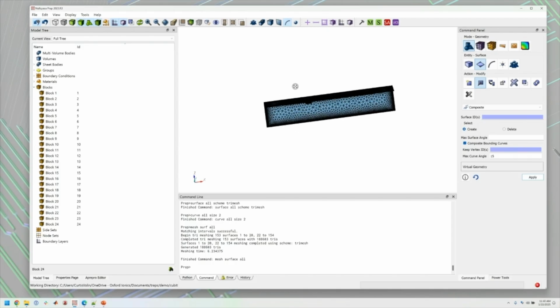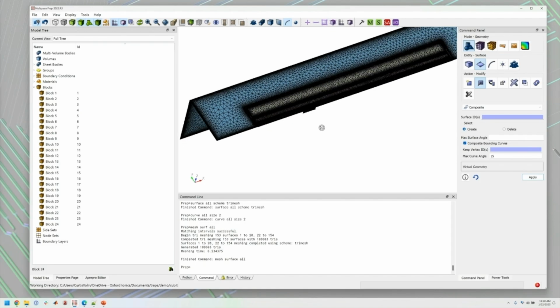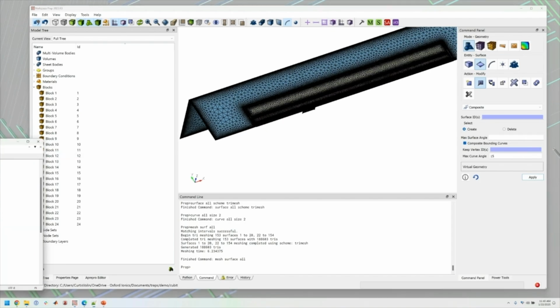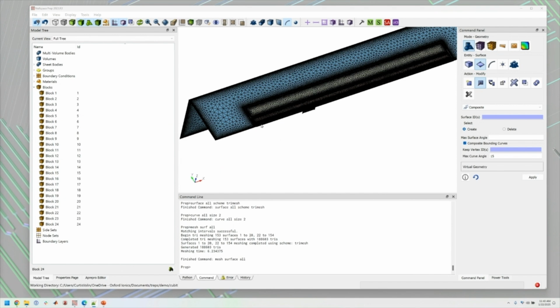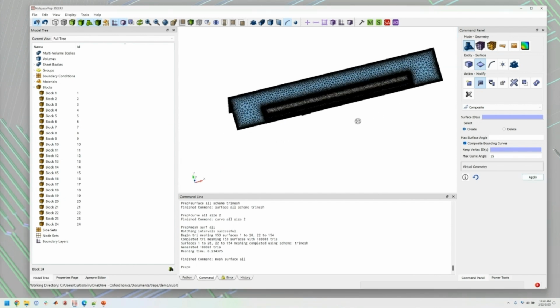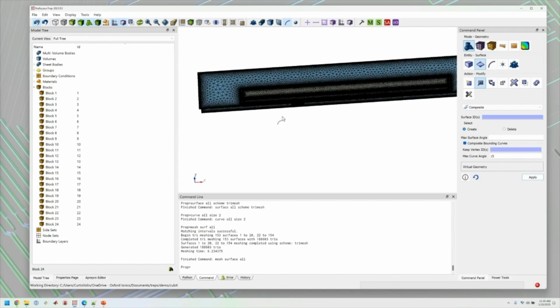If they both need to be present to get the kind of fidelity you want, then one of them can be virtual and the other has to be physically inserted into the model and meshed in order to have that capability. So the other advantage of doing this symmetry plane is that we know that the potential distributions in the volume above this will be perfectly symmetric.